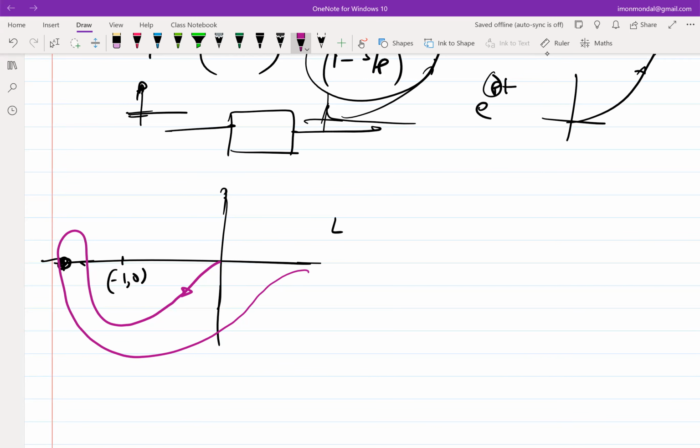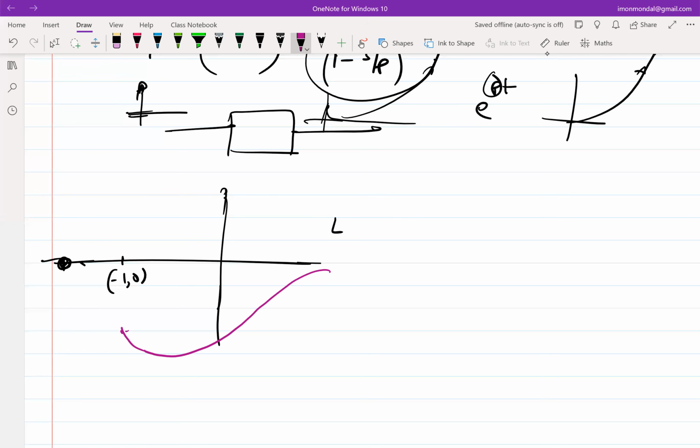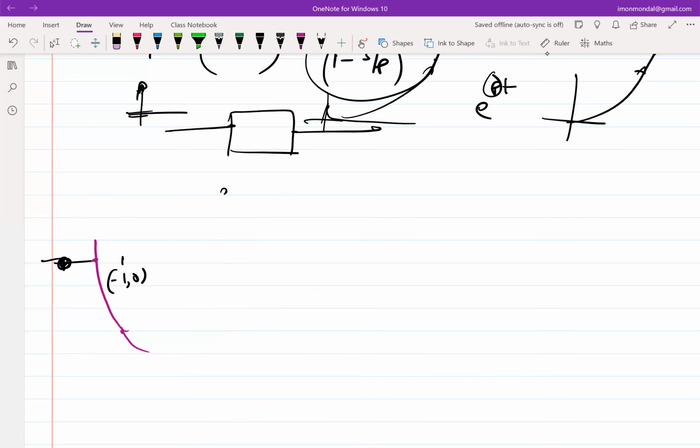Okay. So now the good thing about all pole systems is that phase always decreases. Phase never increases, right? In order to have a phase which is increasing, you need to have zeros, right? So if you have all pole systems, phase always decreases, which means if it goes this way, it cannot come back this way. Right? So phase monotonically decreases, which means in case of an all pole system, if you know that it's -2 then it's unconditionally unstable. But anyhow, that is not for today. We'll not bother about that.